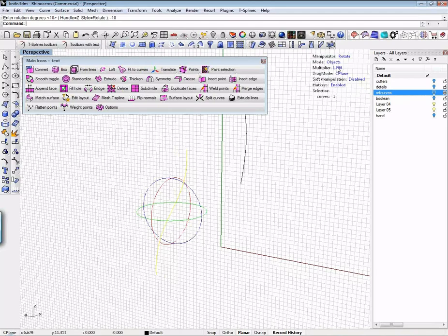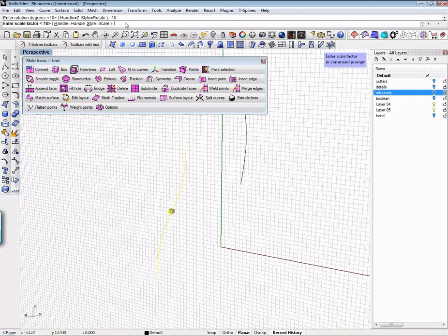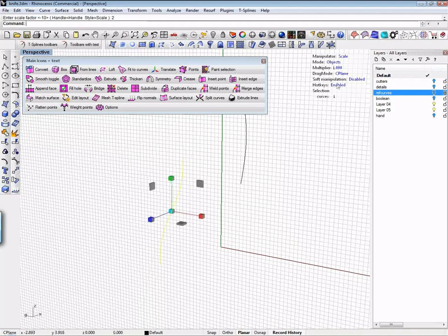Okay? The next manipulator, if I click up here, is the scale. Same thing. I can scale in one direction. I can constrain my scale to this plane. I can constrain my scale to these planes. Or if I grab in the middle, the whole object goes up and down. And again, if I want to do a global scale on this, I double-click it. If I want to double the scale, I type a factor of 2, and I can control it that way. The final manipulator is hidden, which hides the manipulators, obviously, by the name, and then I can just click through and get to those. Now, there are hotkeys for these, but for the purpose of this, I'm not going to be using any of them because I don't want you to get lost on the hotkeys.